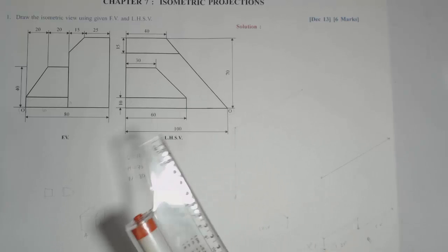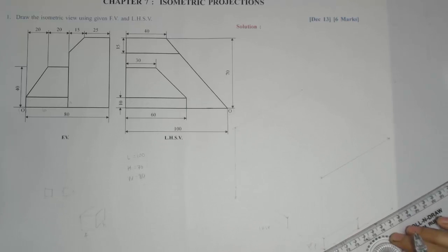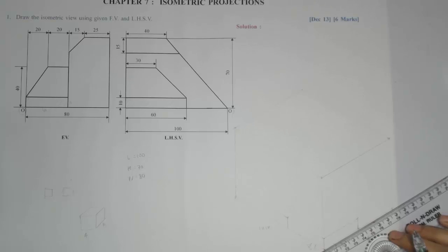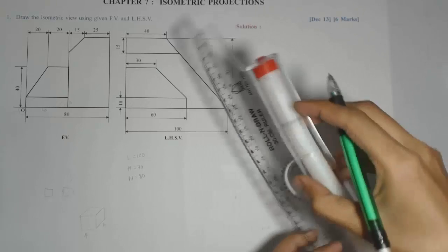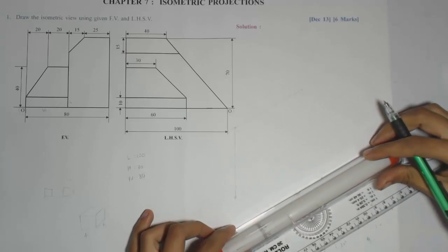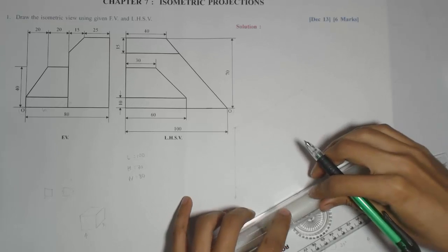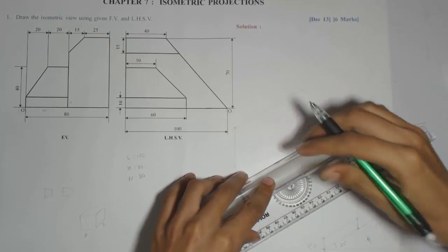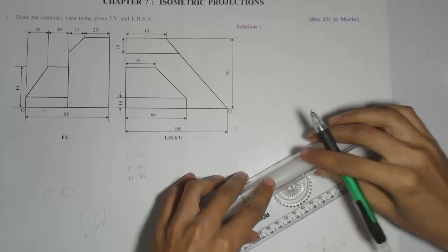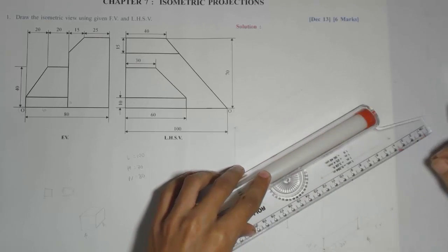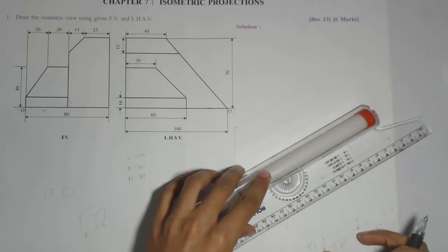So using that method, for drawing those projectors along the width from the lengths we have already marked in the side view, I need to start with this edge boundary of the rectangle, which is the outer boundary. Then using that reference, I'll draw the parallel lines from each corner. Now again, we need not produce along the entire width. I should produce only up to the width of this particular part.